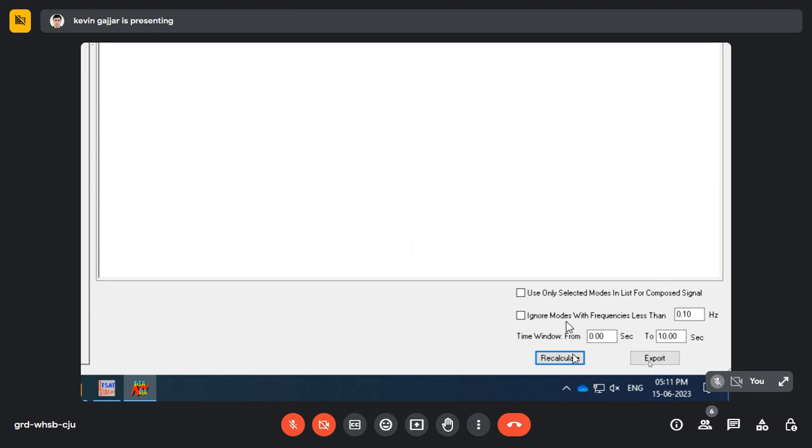It's time domain data. The analysis of the time domain data is done by the Prony analysis, and it will eventually give us the frequency components, the information about the modes visible in the measurement.